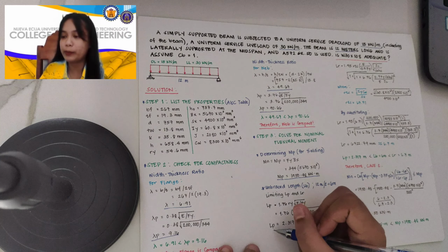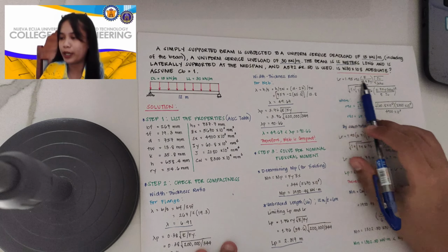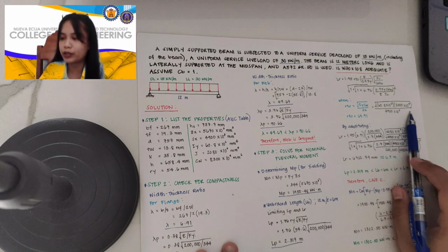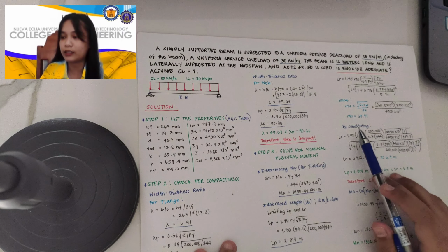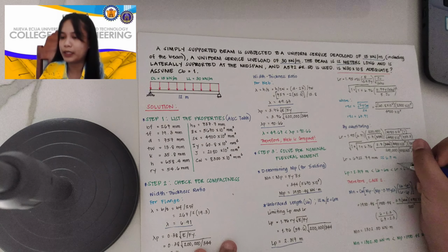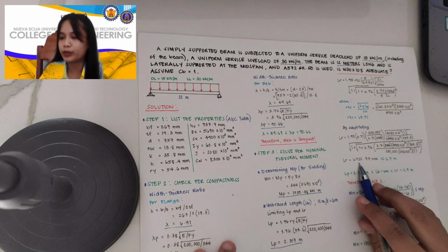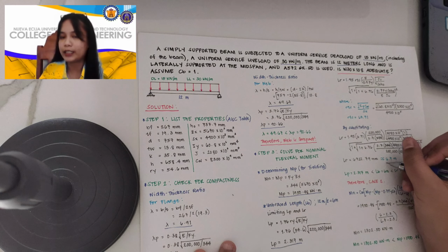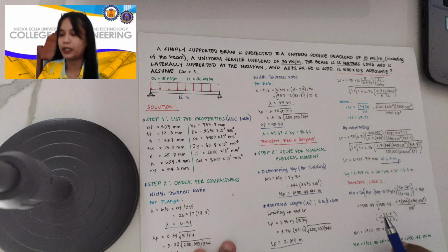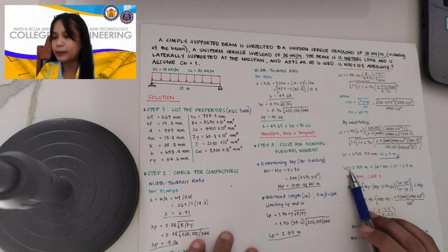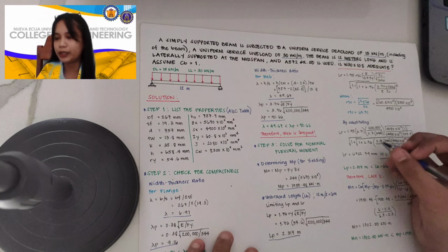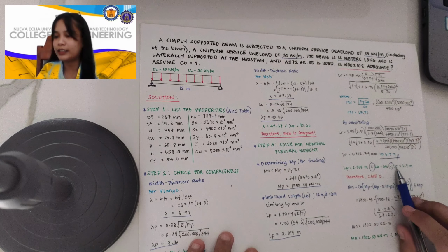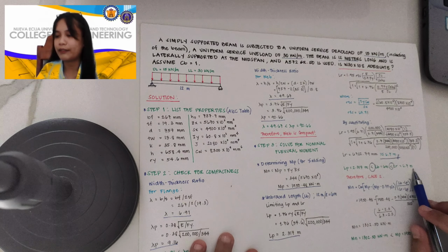So for the Lr, we will be having this formula for Lr. By substituting all the values coming from the properties of our steel, we will be having Lr is equal to 6722.79 millimeter and approximately 6.7 meter. So Lp is equal to 2.317 meter, is less than Lb, which is 6 meter, and less than Lr, 6.7 meter.